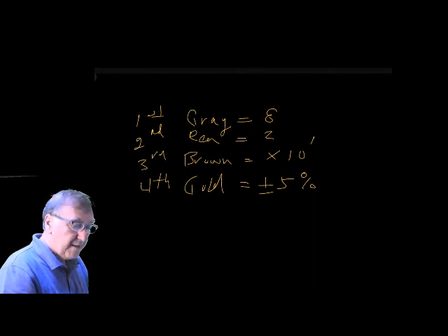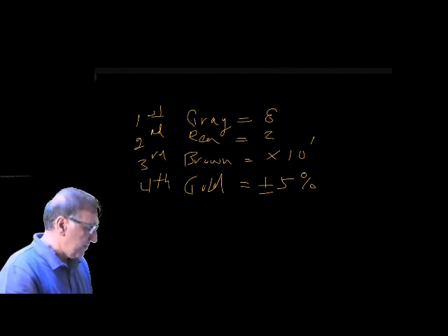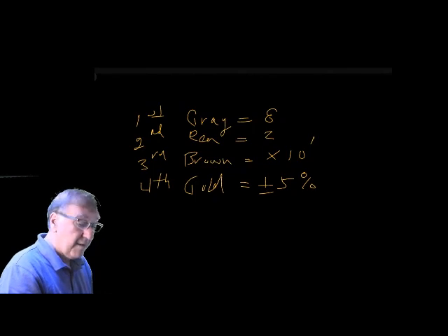So we can see that the bands say plus or minus 5% tolerance of 820 ohms, and we had 824 on the meter, so that is within tolerance.